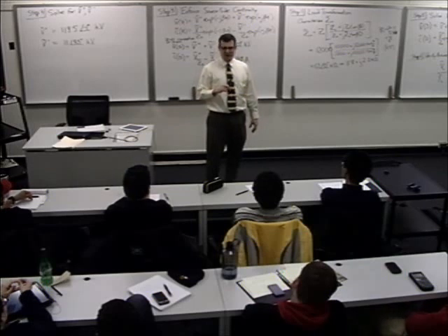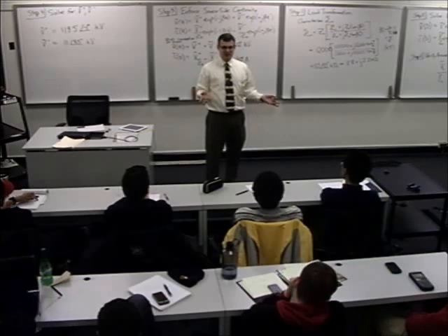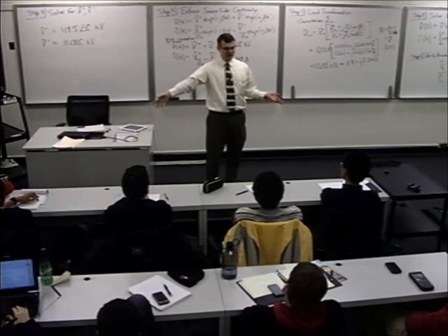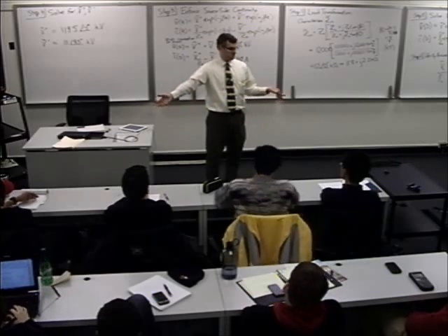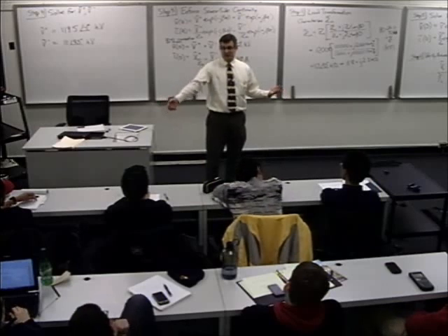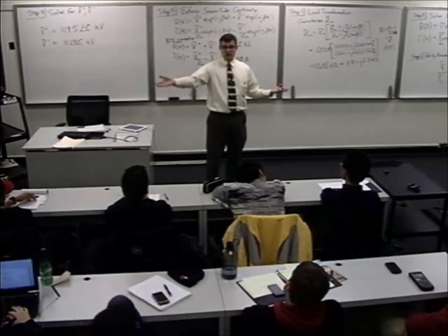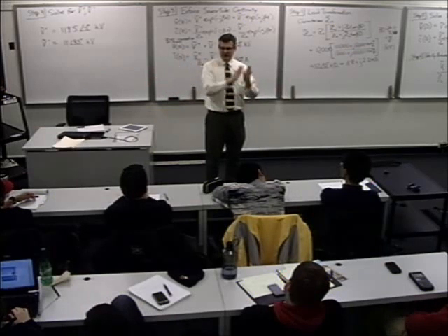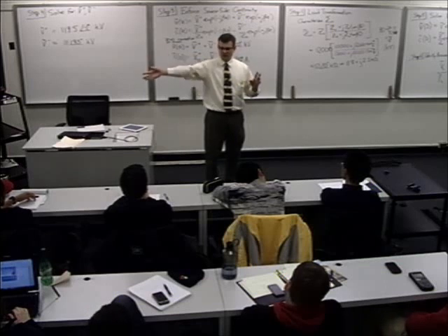So for example, if you're given a homework assignment with a lossless transmission line where something is absorbed by the load, you can use conservation of energy. If somebody asks you how much power was reduced when that cable was damaged, you say the power into this matched transmission line can only go to the load before it's damaged.